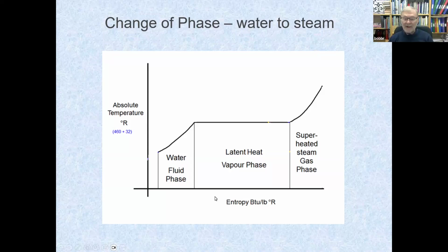We've got the energy and the steam at the bottom. So the more you heat it up, the more the energy increases. So if you take water here at A temperature, incidentally, I use the old-fashioned imperial system because I completely hate, loathe and detest anything metric. So we start here at A temperature and we add, by the fire or whatever means, energy into the water. And at some point, it stops going up this curve and levels out.